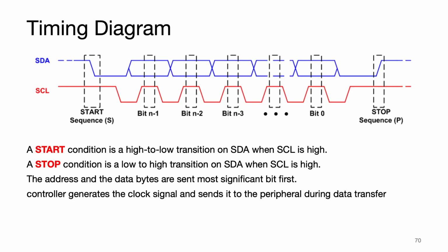Okay, so let's look at some of the timing that occurs here. So here we have the data line, the SDA data line, and we have the clock line, SCL. Okay.